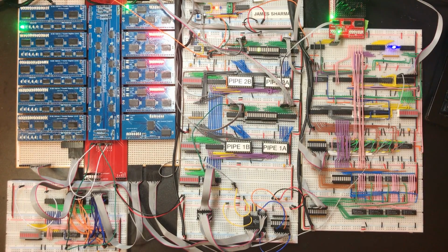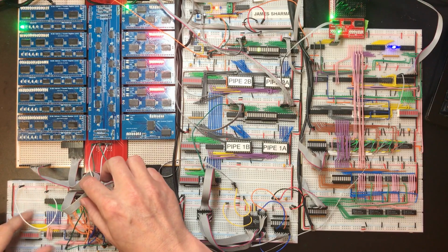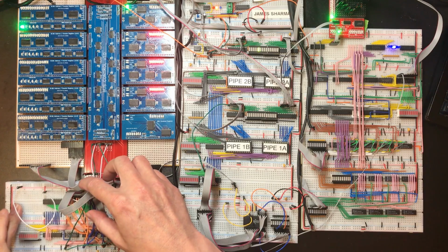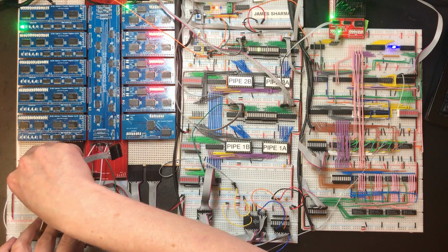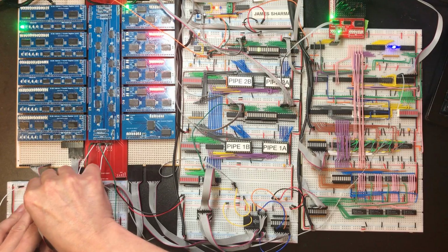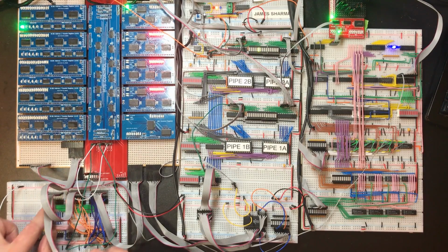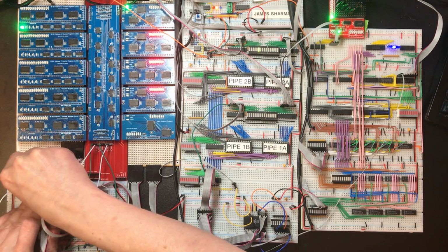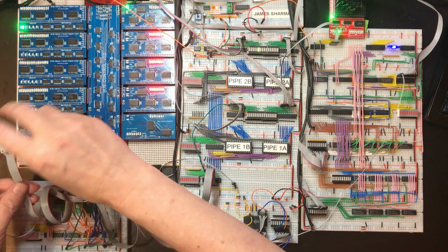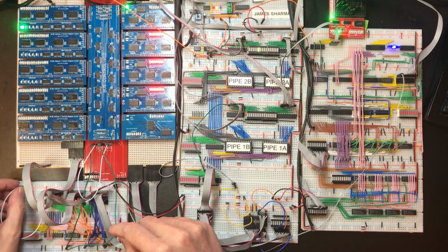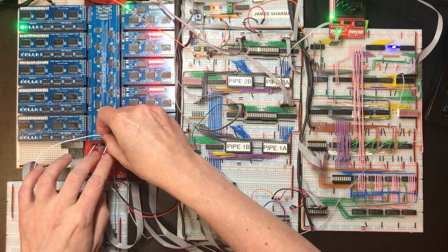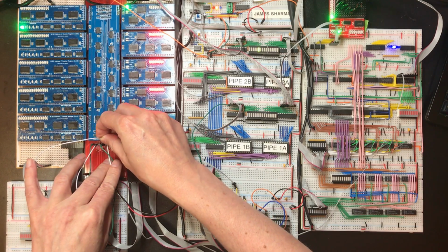Before I go on, I do want to correct one small mistake. When I was wiring in the temporary lower half of the transfer register, I did say there was no spare connection to connect the address bus output, and of course in hindsight I could have just done this. So we've got that connected now, and then I just wire in the assert line and that should be okay.